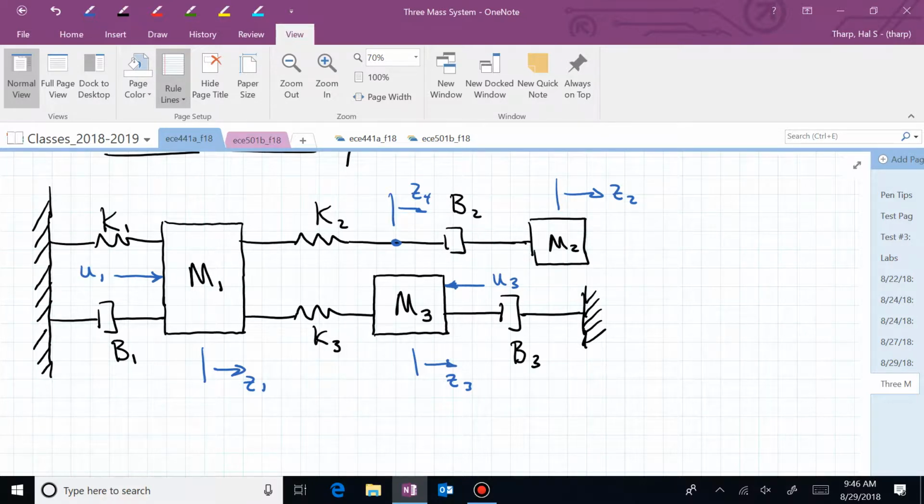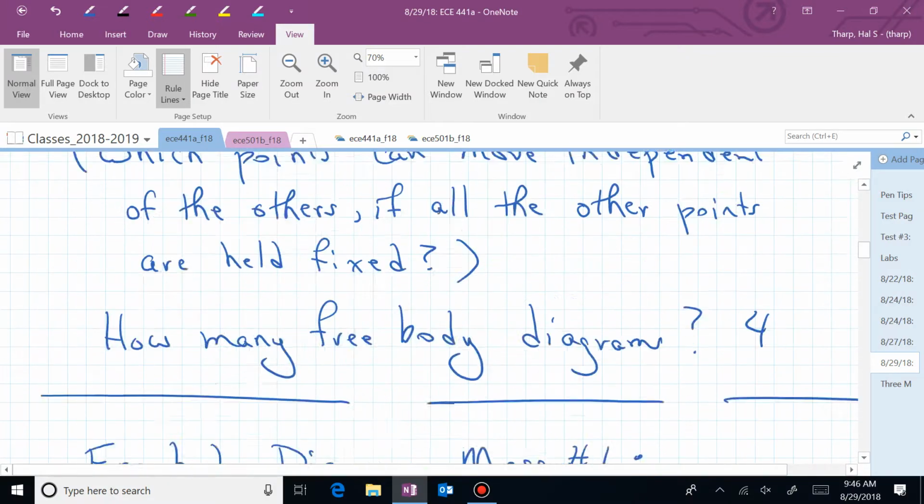And what do I multiply these dash pot coefficients by? Positions, velocities, accelerations. Velocities. So I know that I have to have velocities, single primes. Pull out your spring from your pen again and think about the dash pot, and which way do we have? What's in the parentheses?